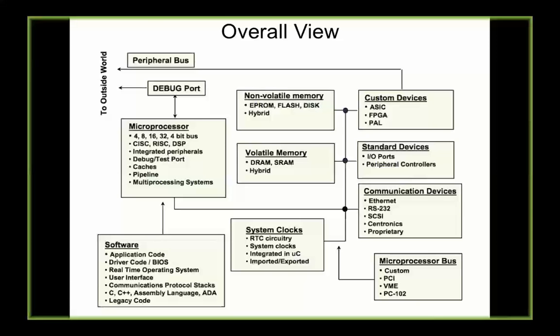On-chip debugger examples are like BDM. Motorola started one term which we call background debugger mode, and then later on it went from proprietary to an open source accepted standard, which is often referred to as JTAG. JTAG stands for Joint Test Action Group, right? It's the IEEE 1149.1 specification, which you can download and understand, the way at the time of CPUs being designed, how do you talk to them?